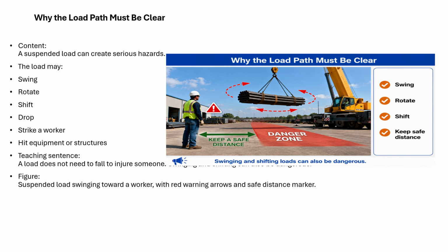Why must the load path be clear? Here is the red area. A suspended load can create serious hazards. The load may swing, rotate, shift, drop, strike a worker, or hit equipment or structures.